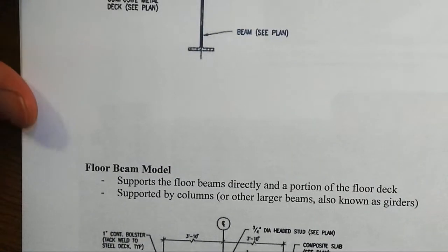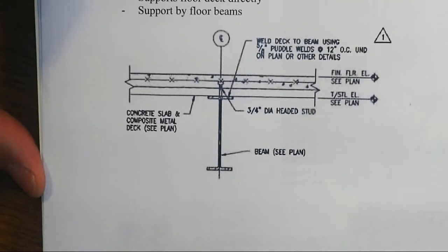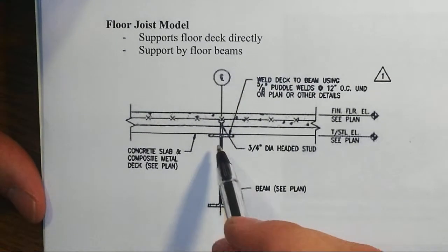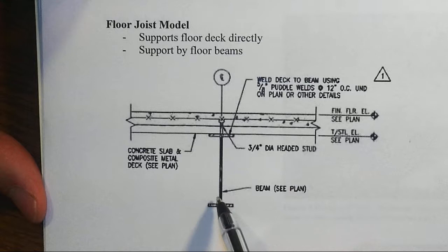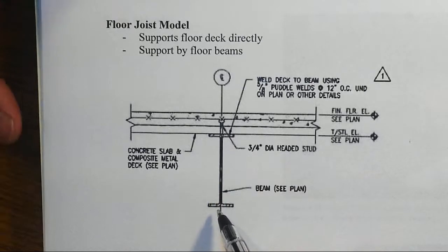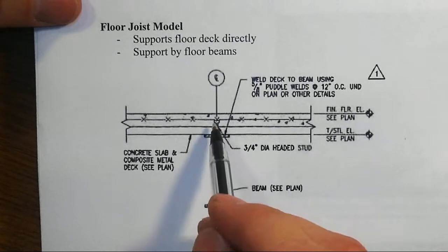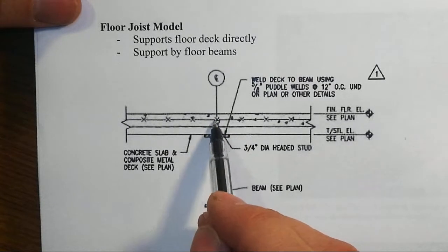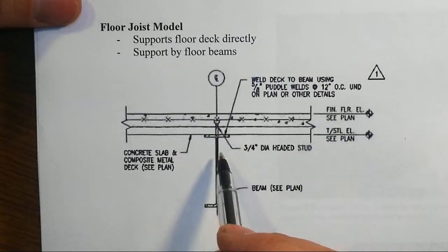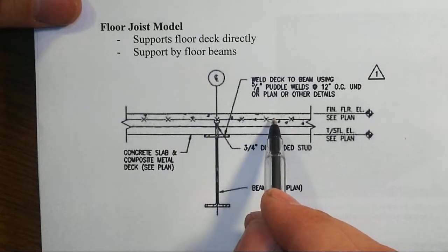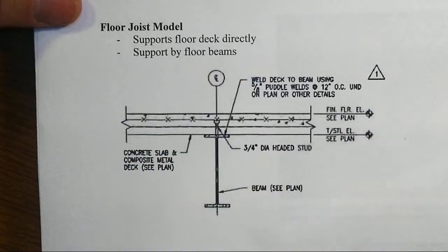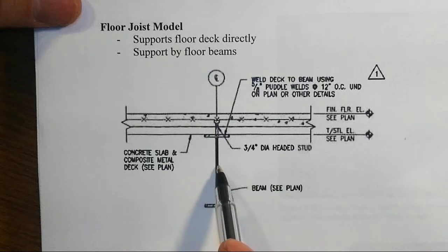Right? For us, though, we're just kind of getting an idea of what these drawings might look like in real practice. The cross-section of one of those floor joists looks like the following. So here's this W18 by 40, that I-shaped cross-section, not an I-beam. There ain't no such thing. It's an I-shaped cross-section. Here's one of these little headed shear studs that's welded through the metal pan deck, and then this represents the concrete slab that this beam is supporting, right?